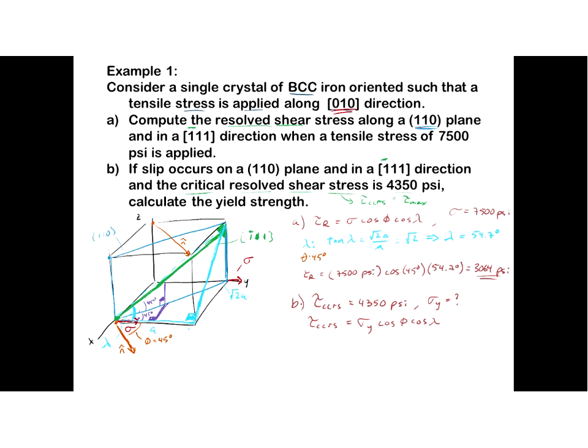All right, and so what we'll do is then, question? Yeah, so what is it if they are 45? The way to calculate the critically resolved shear stress is to assume that they are both 45, unless they're given already. If you have actual planes and directions, then you have actual phis and lambdas, and those are the ones you work with.